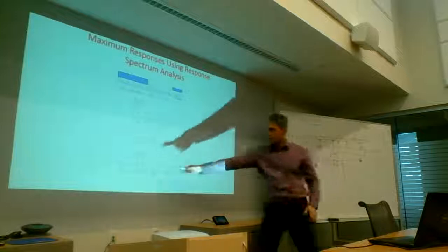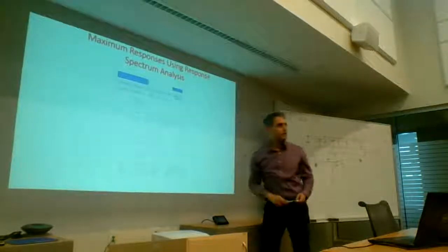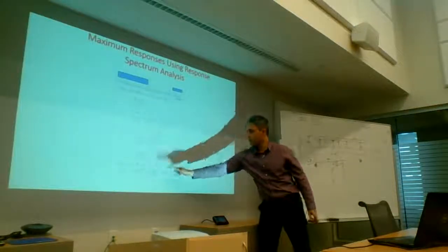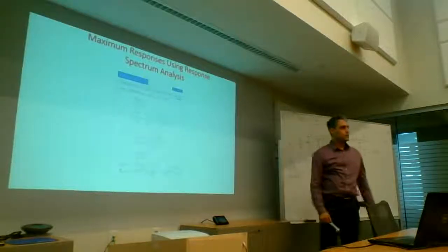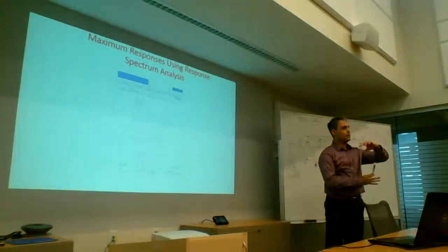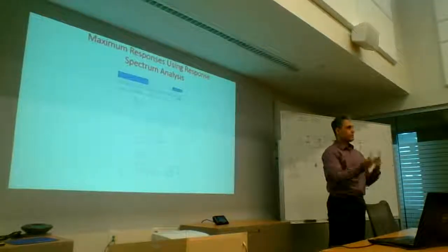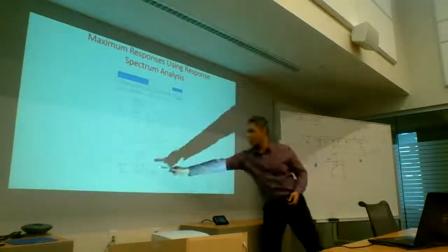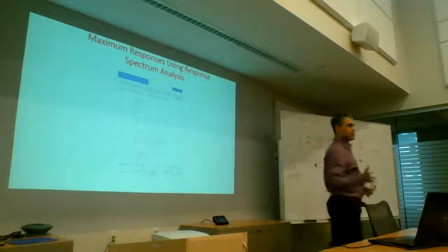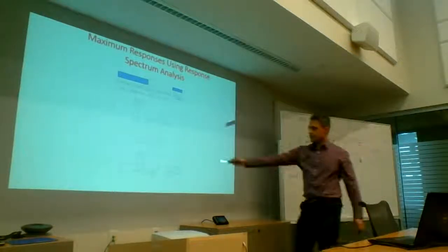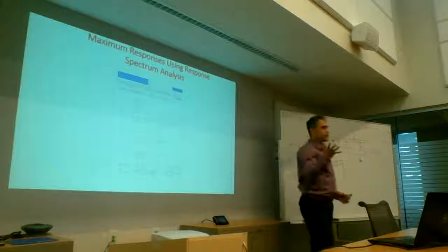You see this, to get your displacement, you're multiplying this P1 with the Phi1. Okay, so when you change the Phi1, you get a different P1. You can keep changing those, you'll keep getting different combinations, but the P1 multiplied by Phi1 is going to be the same. And then there is SA over omega squared, which is constant.